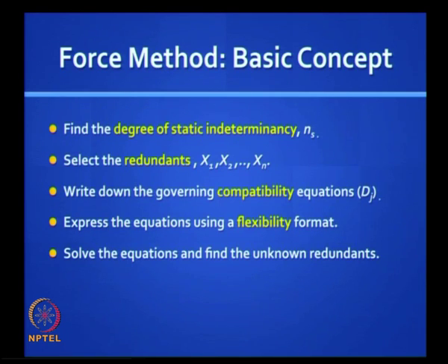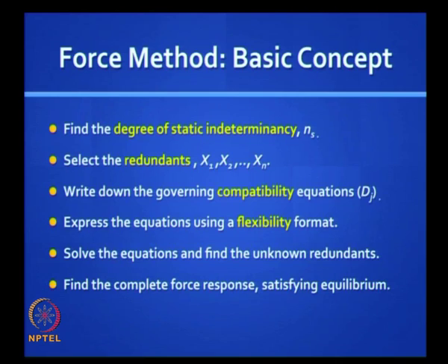You could do it directly on that overall free body. Alternatively, you could find out what is happening under the action of each of those loading systems on the primary structure and superpose everything. And so you find the complete force response. It satisfies equilibrium, but more important, it also satisfies compatibility.